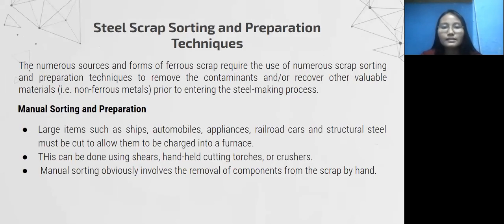So this is the scrap sorting and preparation technique. The numerous sources and forms of ferrous scrap require the use of numerous scrap sorting and preparation techniques to remove the contaminants or recover other valuable materials prior to entering the steel making process.